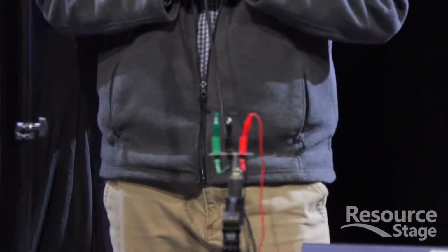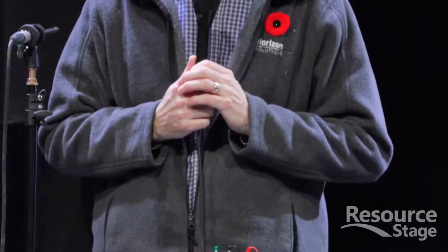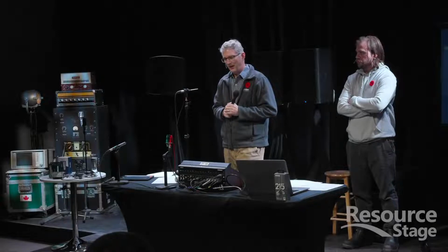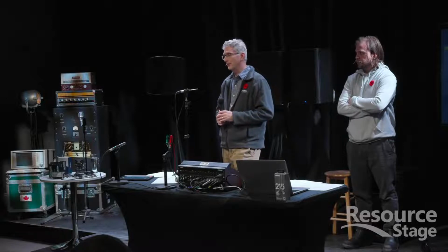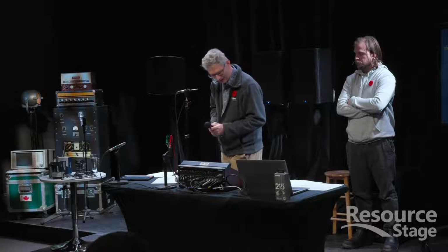So if you ever plug in something and you have that problem, it's a good idea to test your cables and find out what it is. We'd done an install recently, and I discovered that on one of the microphone inputs, I had plugged in my noise source, and the system just sounded really, really thin. I couldn't quite figure out why. We did a little bit of investigation and discovered one of the conductors hadn't been terminated properly. So we fixed that, and it was working just fine. So good idea to check that.